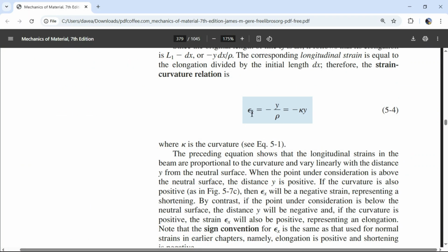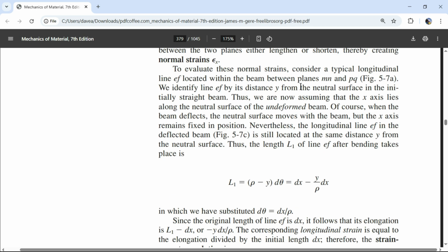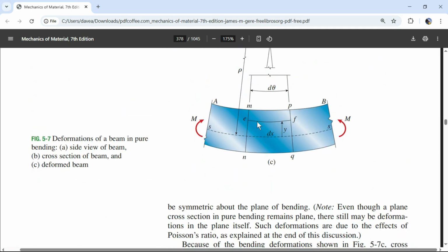So this is the strain at some value of x. When we go up into the y direction, we're going to get a strain at that point. It's not a function of z, so if we move in the z direction, in and out of the board, the strain widthwise is going to be the same.